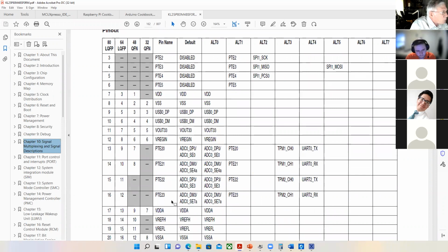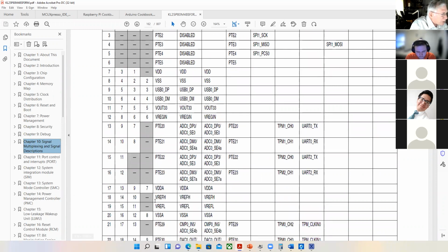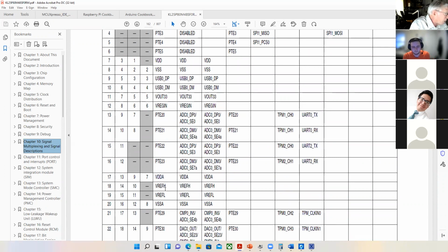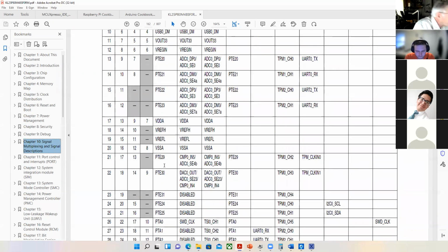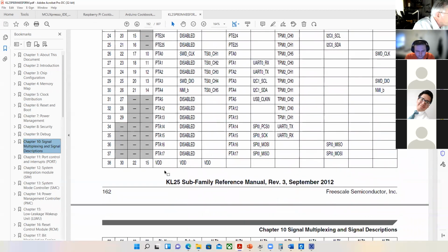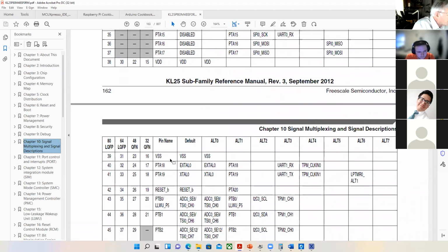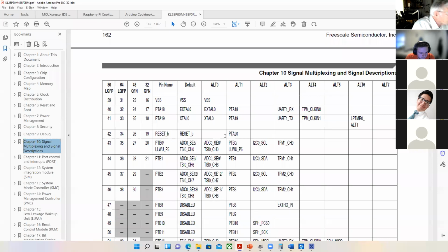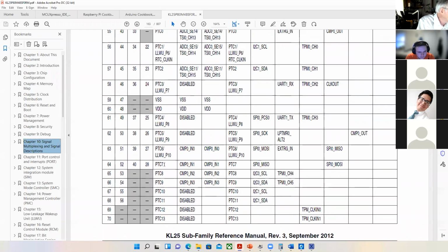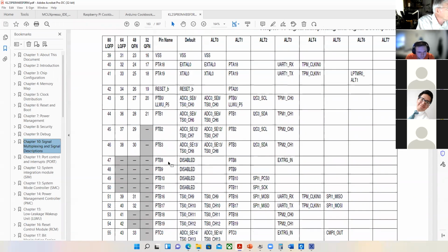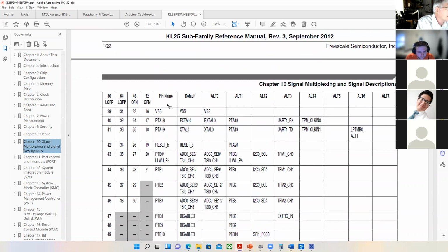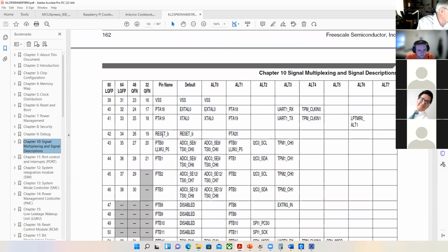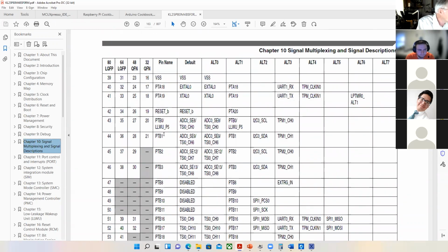Here's the port E pins. Here's the analog power in, analog reference high, analog reference low, the analog ground. And then here's E29, here's A's, here's another power pin, here's another ground pin, here's 18. There's a reset pin. It's actually also pin A20. And then here's pin B, pin C, a few other things. Okay, so every one of these pins generally has a name that's either GPIO related or power or ground or analog power and ground or USB related or reset.